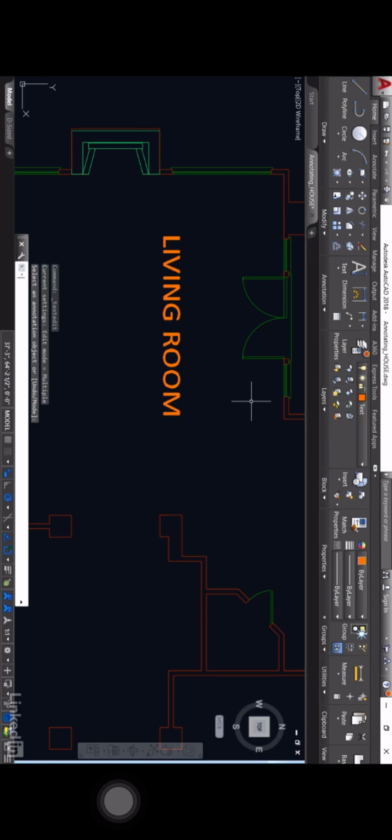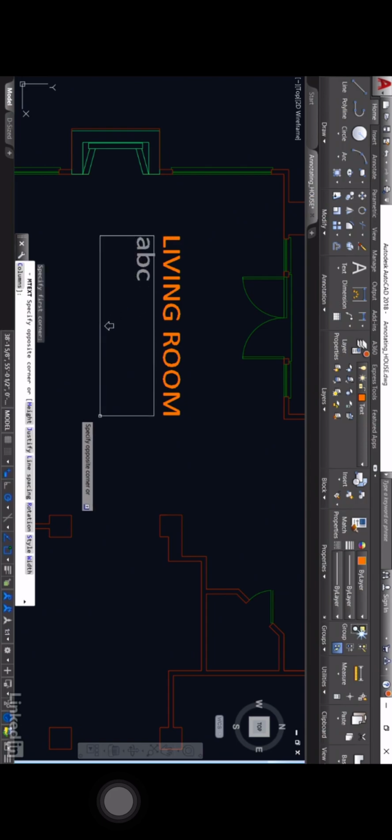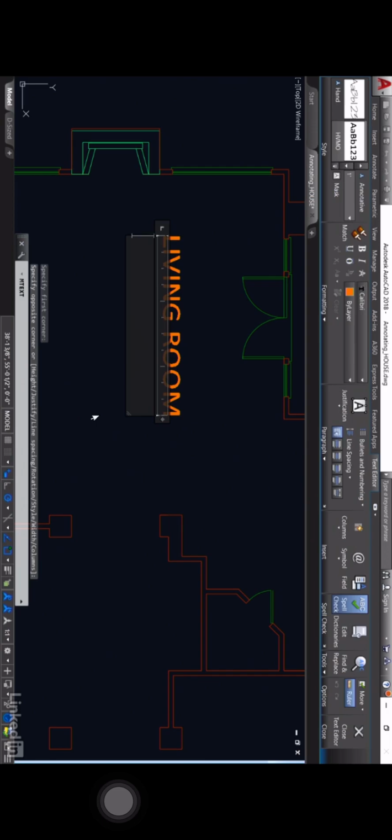What about multi-line text? So again, I click on the flyout and I go for multi-line text. This time I need to specify the area of the text. So I'm going to click once here and drag across here to get the text into that box there. Still get a flashing cursor, but you'll notice that the ribbon changes this time and goes into the text editor. Multi-line text is much more like something like Microsoft Word, so there's lots of tools for styling, formatting, paragraphs, and so on.